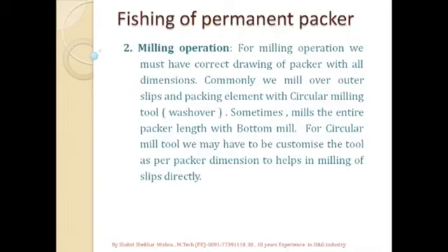So we have a very small annular space between casing and the packer OD. Accordingly we have to design or select the washover shoe.